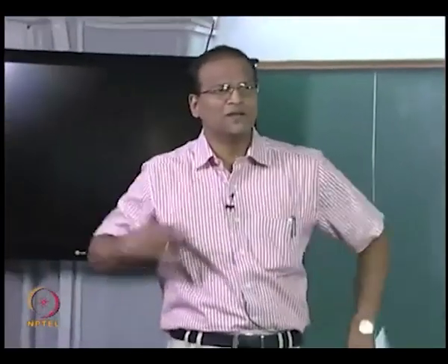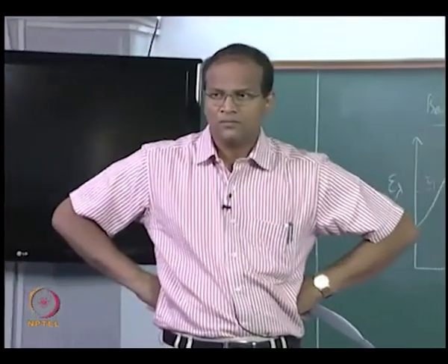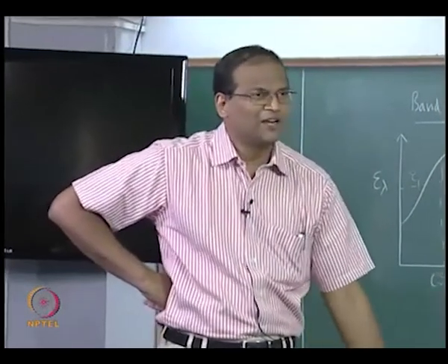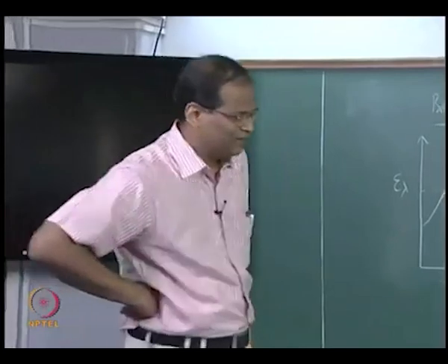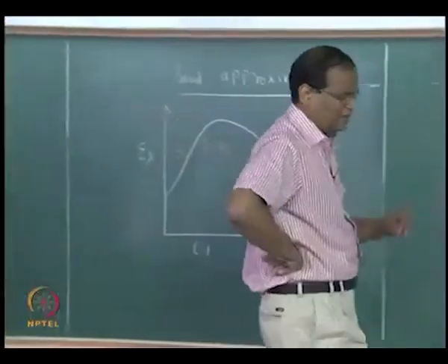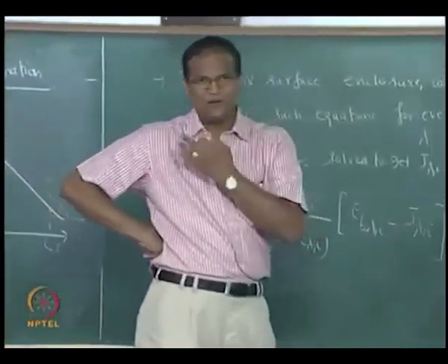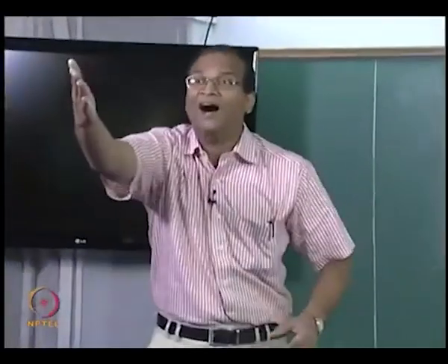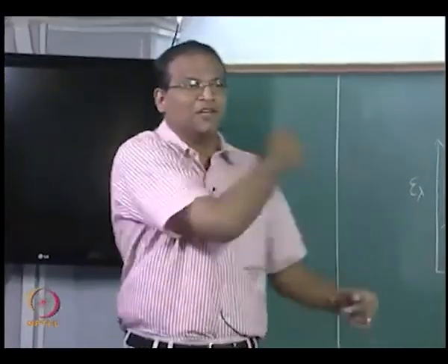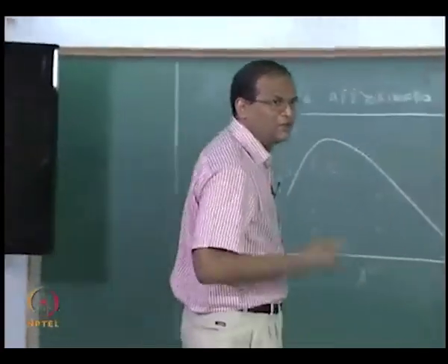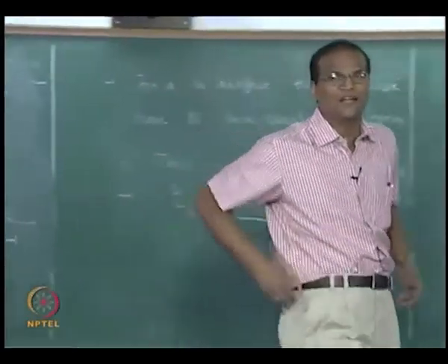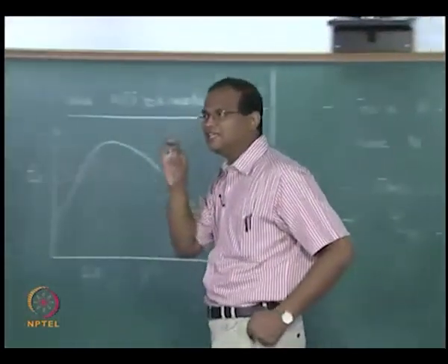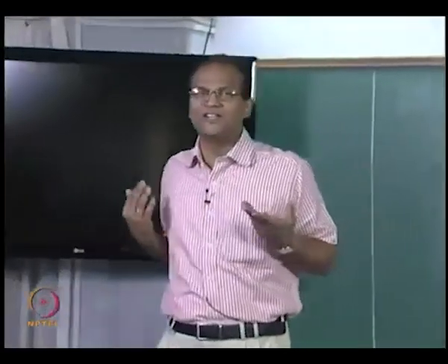What is the major achievement? Instead of integration we can do summation. Hit the bullseye. What have we done mathematically to a continuous function? It's a piecewise constant emissivity model. So a continuously varying function has been converted to a piecewise constant emissivity which can be easily handled, and I know I can use the f function chart.